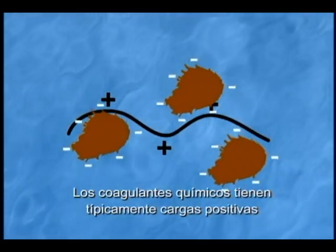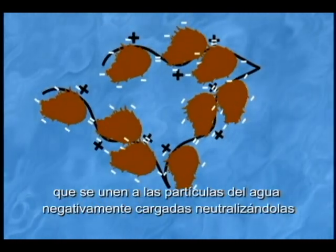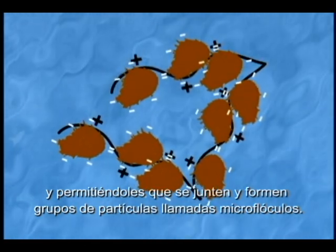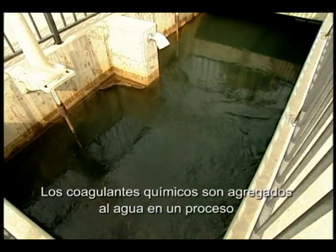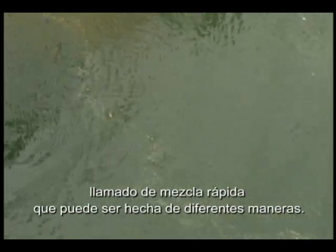Coagulant chemicals typically have a positive charge, which binds to the negatively charged particles in water, neutralizing them and allowing them to come together to form small clumps of particles called microfloc. The coagulant chemicals are added to the source water in a process called rapid or flash mixing, which can be achieved in several ways.